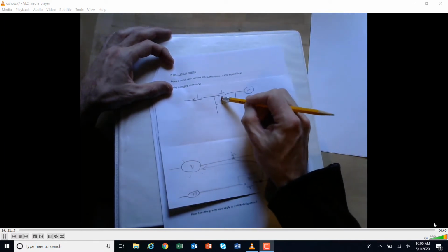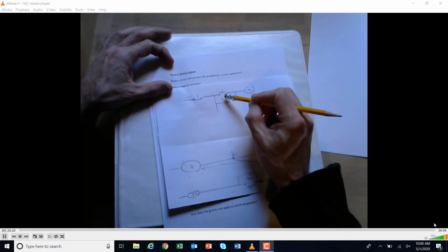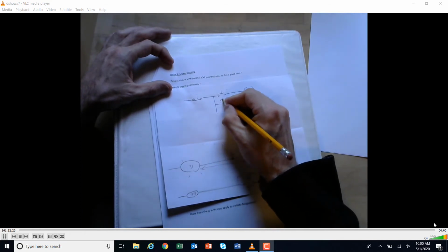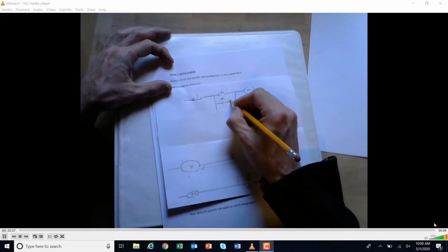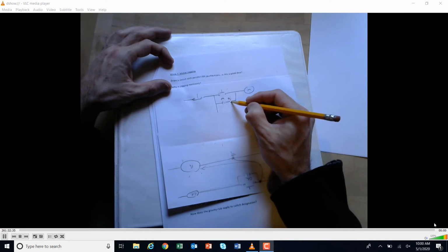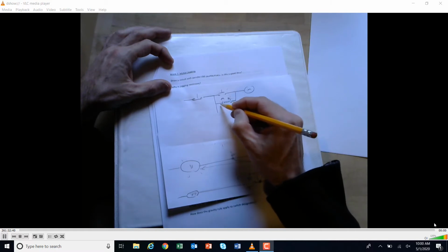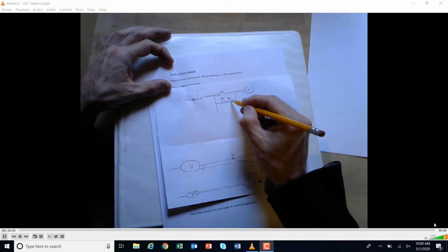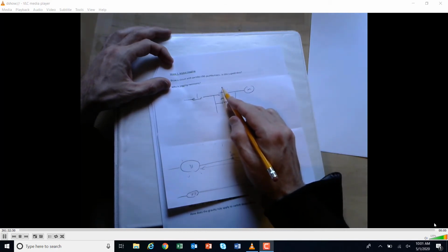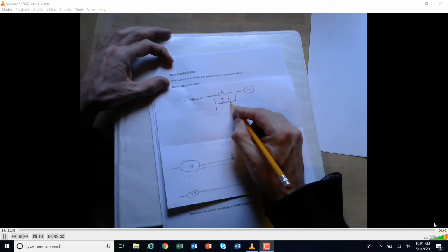Let's fix this again. Sorry, we have a motor. What we would have here would be some type of selector switch, so that we could select this function on or off right here. If this was clicked up, basically we've created the opportunity to have memory on the circuit. And when we open it, then we don't have memory, so that this button would act either as a run or a jog, depending on this, okay?